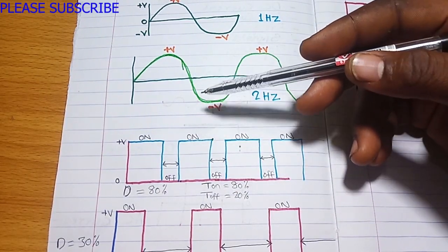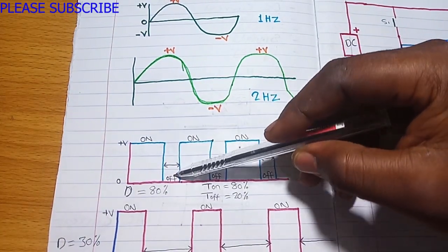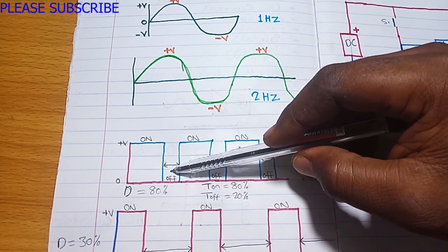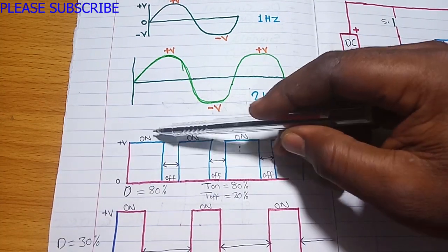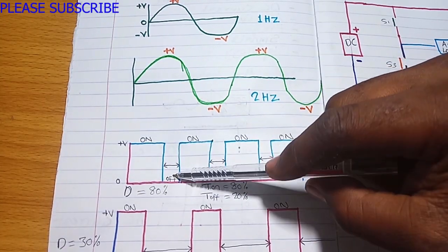It can be a sine wave, it can be a modified wave. So this is the on time, this is the off time, and the space between the on time and the off time is what we call the duty cycle. Okay, so this signal is 80% on and 20% off.